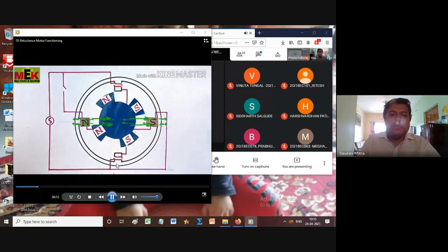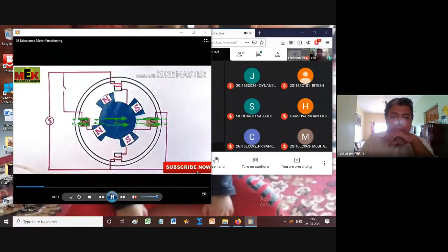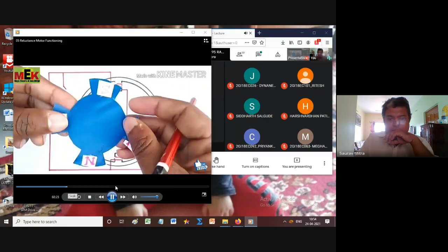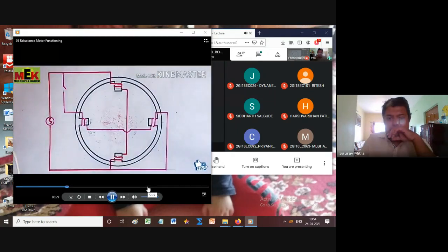Here the main problem he has created is that he has shown 4 stator poles and 4 rotor poles. This I don't like, because the stator poles should be more. Stator poles should be 6 and rotor poles 4 is okay. But this fellow has used a very unique kind of explanation method. I will show you that. So I will run the video a little. Whenever you are drawing, please draw 6 stator poles and 4 rotor poles. That will do.